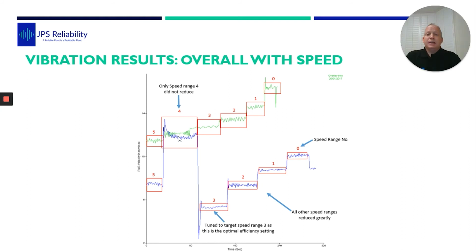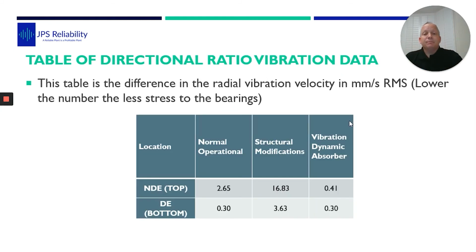But what you will see here, strangely, is number 4 is back up there. Well, that shows you you could design as much as you like in theory, but without putting it to practice and testing it, you don't know what's going to happen. But at set point 3, where she runs all the time, it was the lowest vibration, so we were very, very happy with that.